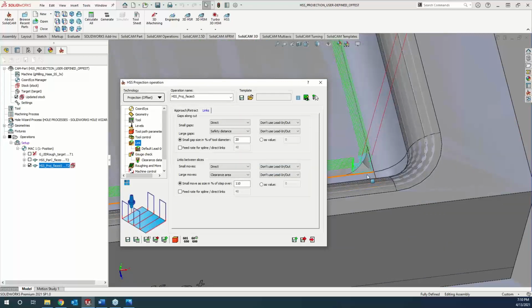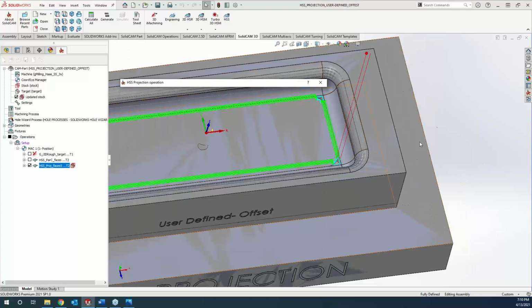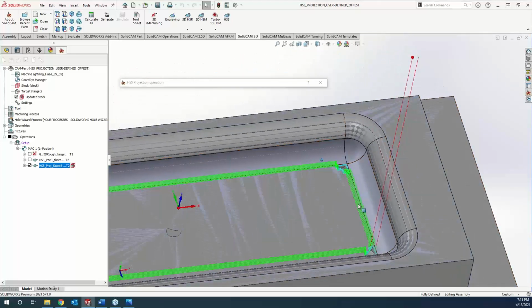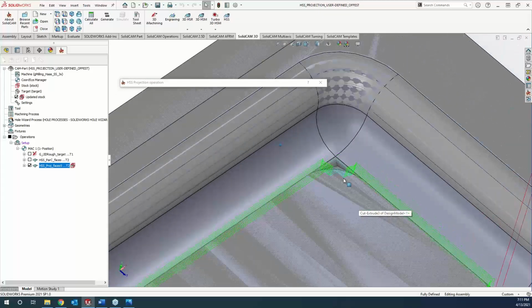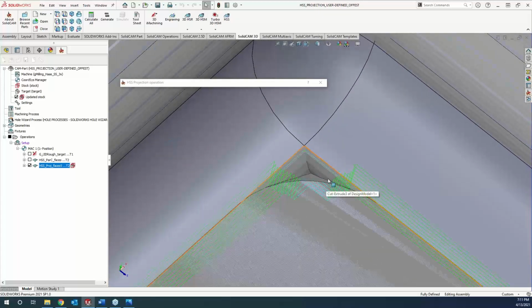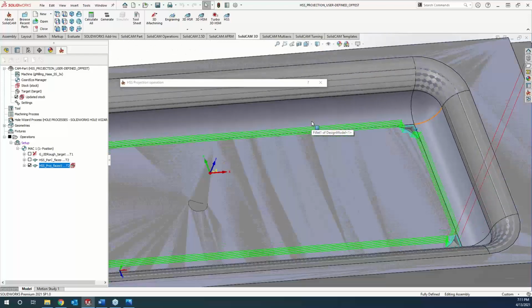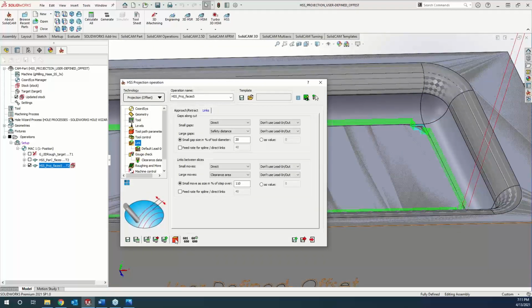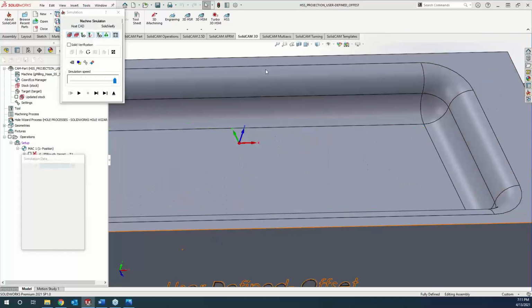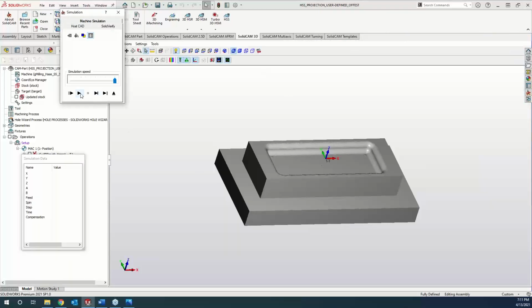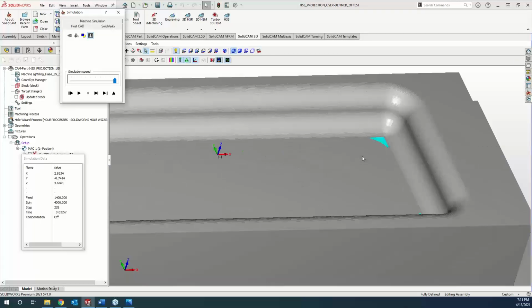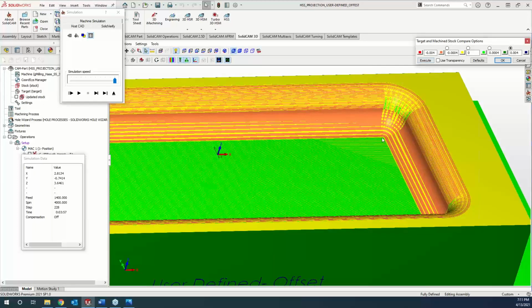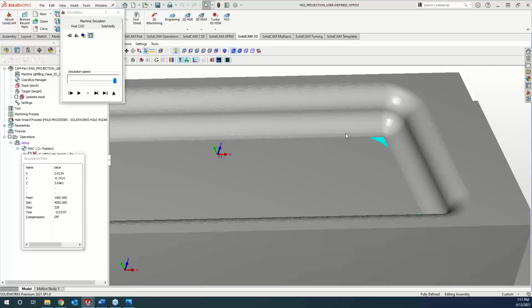And there we go. So now we can see in there that the software is doing all the work for you and trimming out any additional path using a high feed movement and just coming in here and nailing out these corners. So now if we look at this through our simulation here. So now you can see we're just getting those corners. We can do our stock target comparison. We're up to size, as well as we're not dragging that ball end mill across a finished